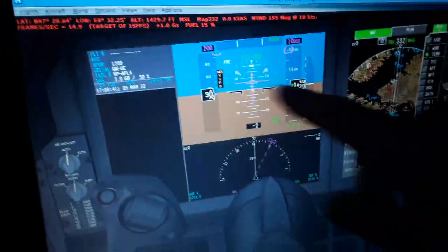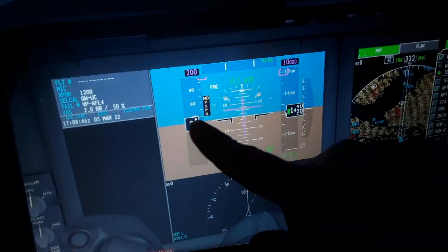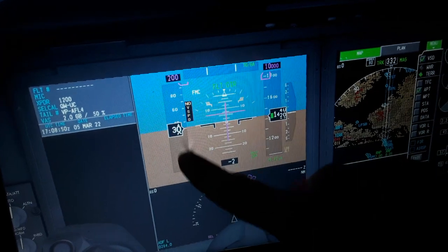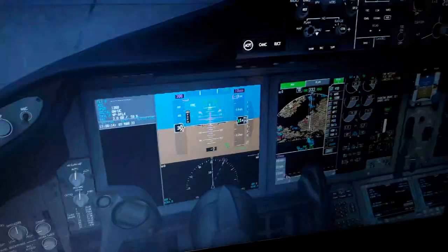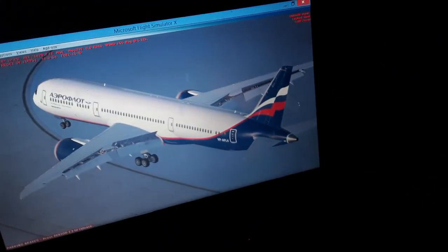So you need to monitor the airspeed tape over here as you fly all the time. You see the airspeed indicated, then you have the stall speed displayed with an amber and a red indication below the airspeed in the airspeed tape over here. So this is the stall. You can see it later in flight. So we have a few more things to see.